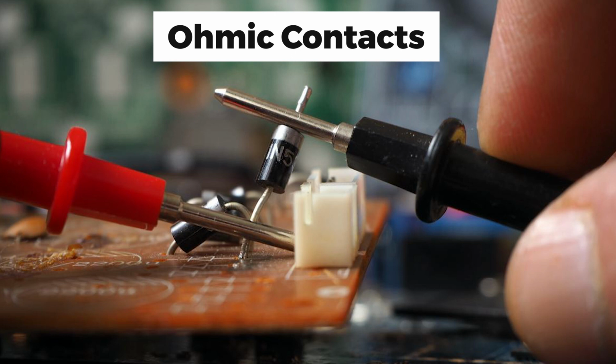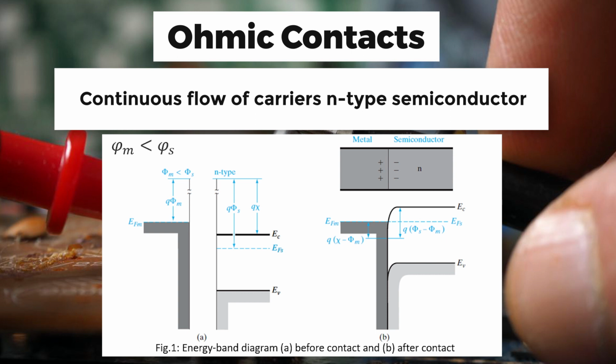So, ideal metal semiconductor contacts are ohmic when the charge induced in the semiconductor is aligned with the Fermi level provided by the majority carriers, as shown in figure 1. Here we can see there is a metal and there is a semiconductor. Let's suppose the example of an n-type semiconductor. In the figure, when a metal is brought in contact with an n-type semiconductor, the electrons from the n-type semiconductor come to align the Fermi energy level. Here we can see that in an n-type material the negative charges come.